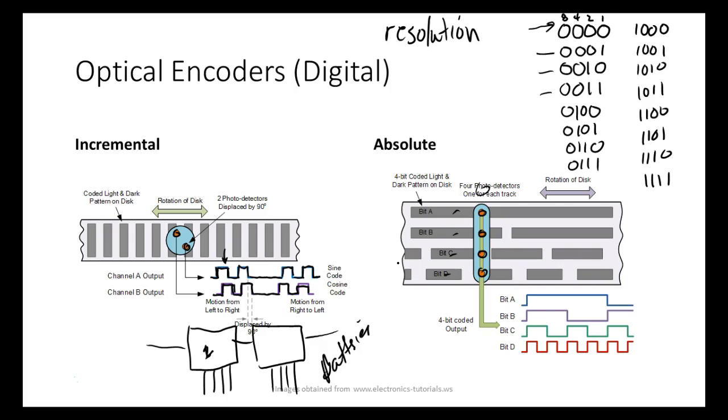With the batteries, we still might have a problem. If you work in a plant with a bunch of robots, one of the preventive maintenance tasks would be to go out there and change the batteries in the robots. Usually it's recommended, some do it every 6 months, a year would probably be good on most batteries. If you leave your robots on 24 hours a day, then the batteries are not used. The only time the batteries are used is when you do what? You turn the controller off.